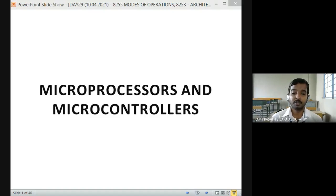So using those control word formats, we can form a word that can be written into where? The control word has to be written into, not A, not A. Yes, control word register. I think Anthony Surya is saying it has to be placed in the accumulator register, then we have to write it in the control word register. Is it correct, Anthony Surya? Yes, okay. So whatever control word you are forming, first the accumulator will hold it, and using the OUT instruction we can write it into the control word register.